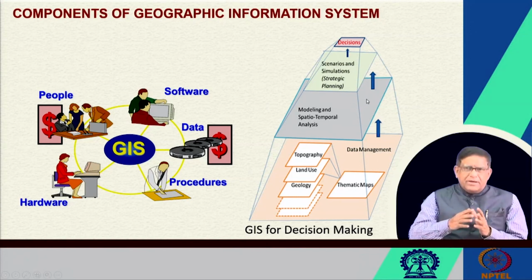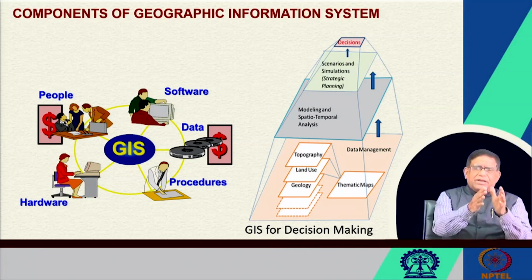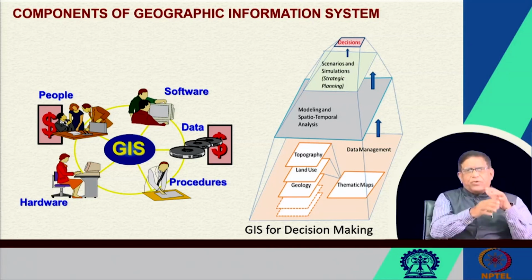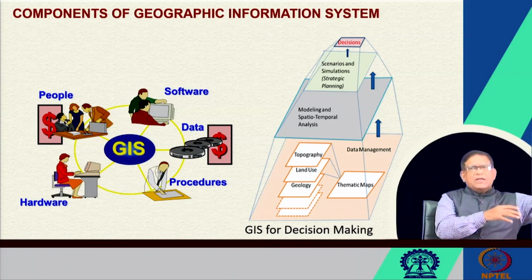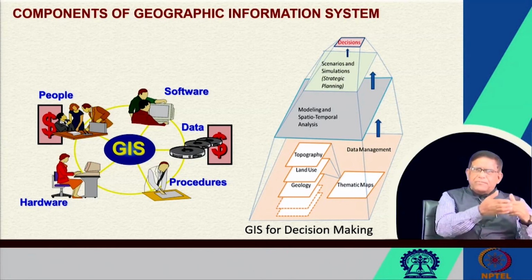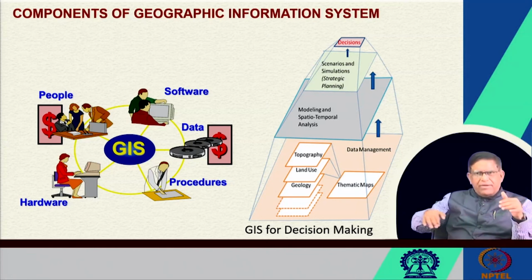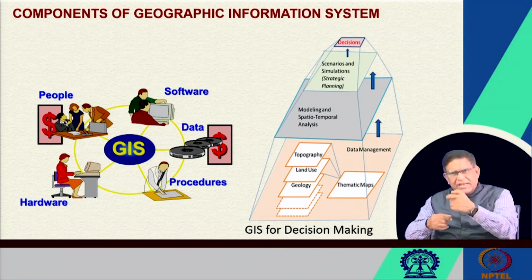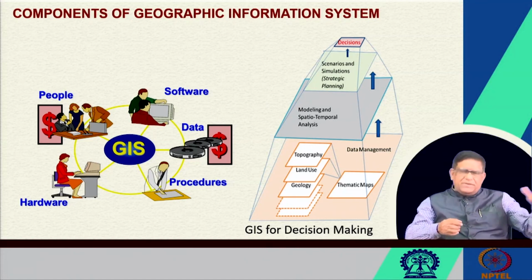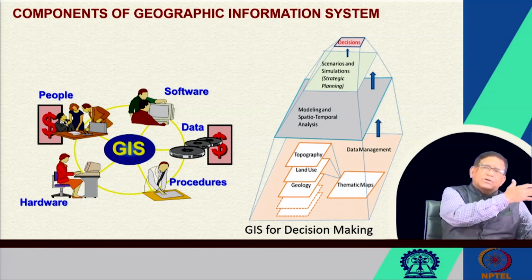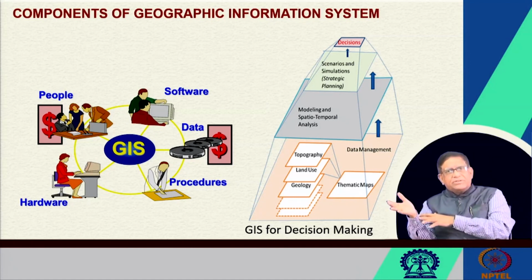If the road goes in this particular direction, the dust generated from the road and tire interactions, because of the wind velocity in this direction, will affect the villages and schools over here. Now, if you make the road go a little away from there, against the wind direction, the school will not be affected, the township will not be affected, and the dust will go towards a forest, so you can change the orientation of the road.